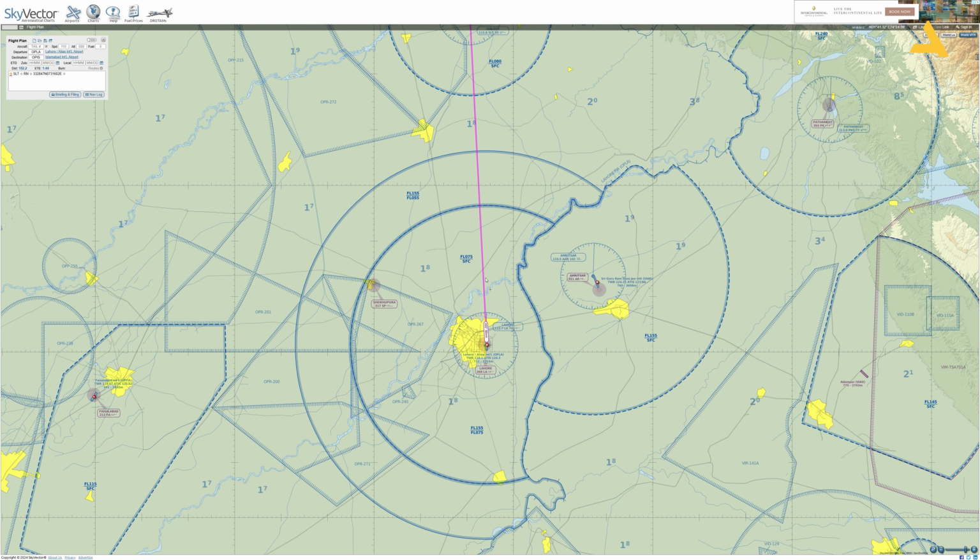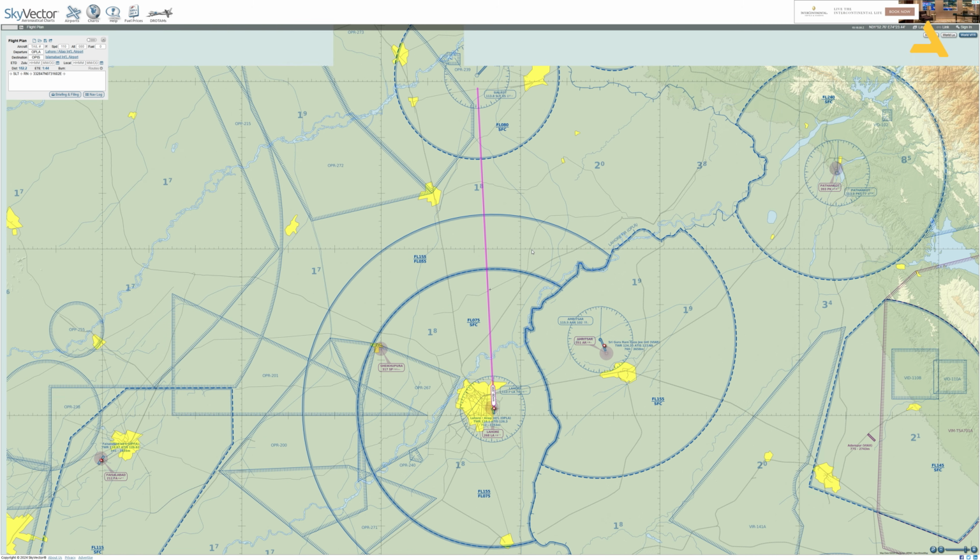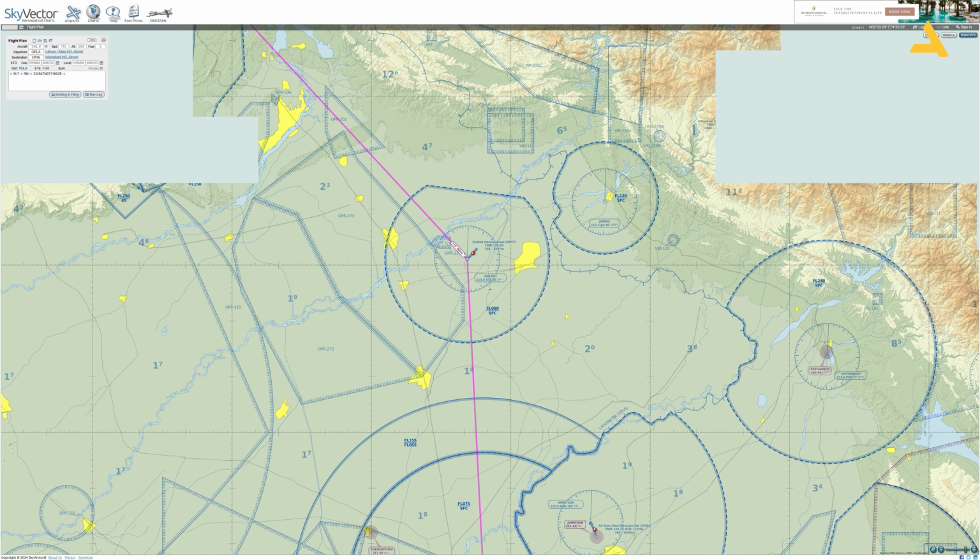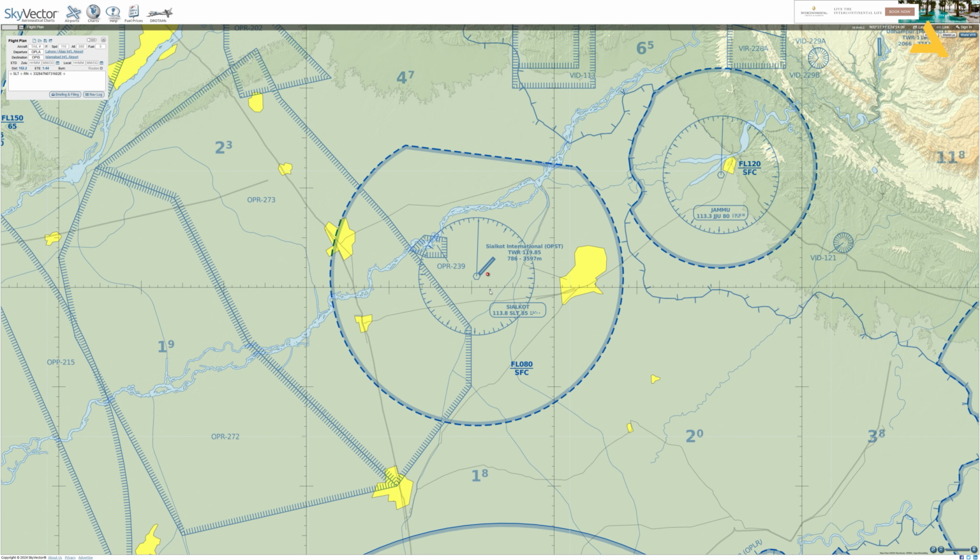following this radial. Now there is something really interesting about VORs. There is a concept of radial in and radial out. So let's consider that you are here. If you are moving towards this side, let's say, your outbound radial is 0 or 360 degrees, because you're going outbound from this.